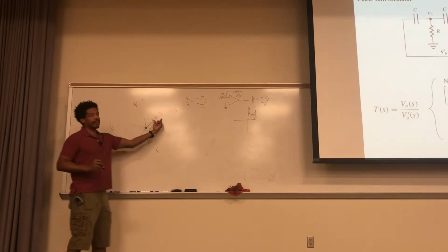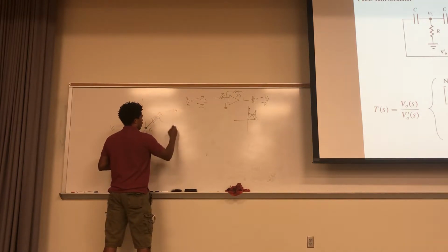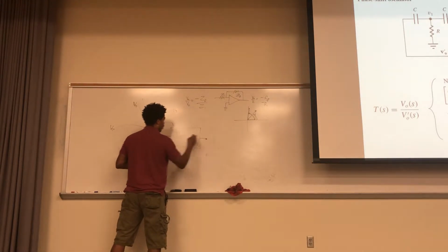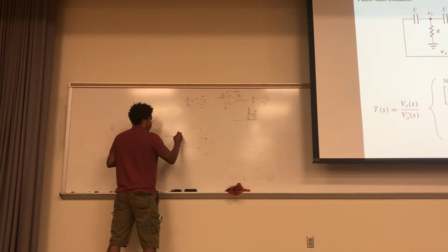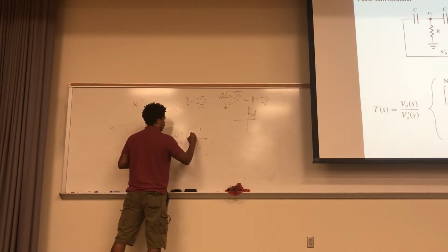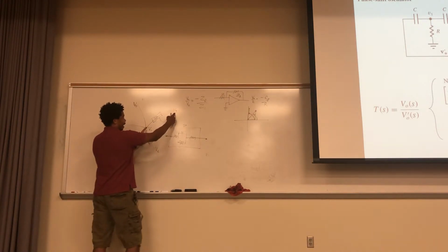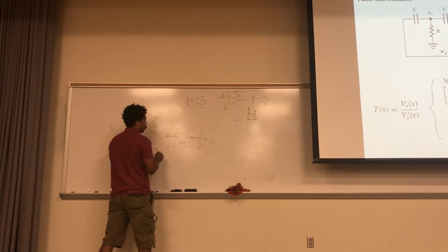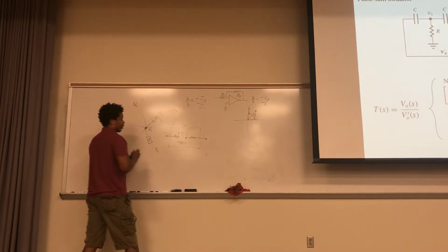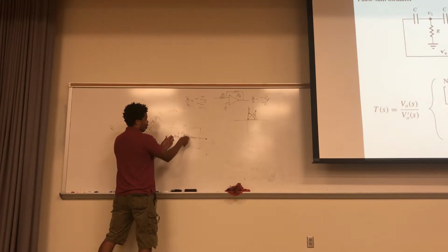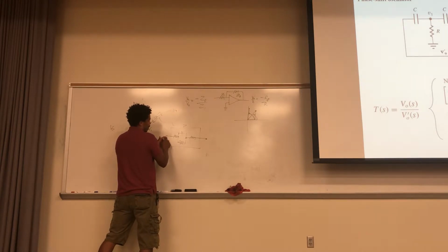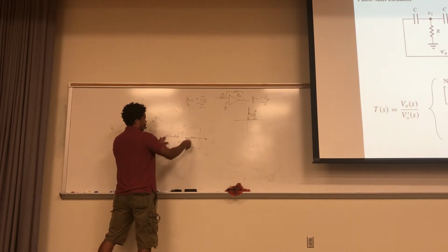And these impedances, it doesn't have to be a single element. Like this Z right here, it could be like a Z where you have the beginning part, the end part, and inside, you can have all kinds of weird things going on. You got things in parallel, right? You can have all kinds of things, but you're gonna call it Z between two nodes. And that means, of course, you're ignoring what's inside. So yeah, you can skip nodes, as long as everything in here is passive. You can skip it and just say, hey, this node, that node, and that node way over there. As long as everything in here was passive, then you're fine.